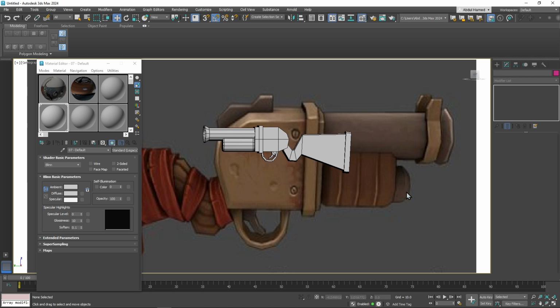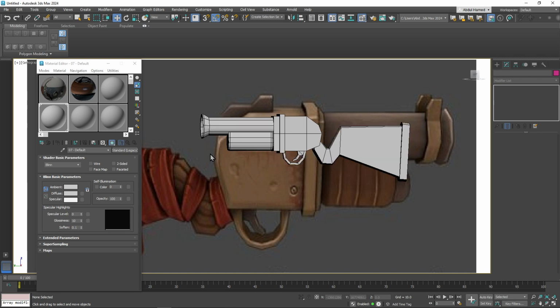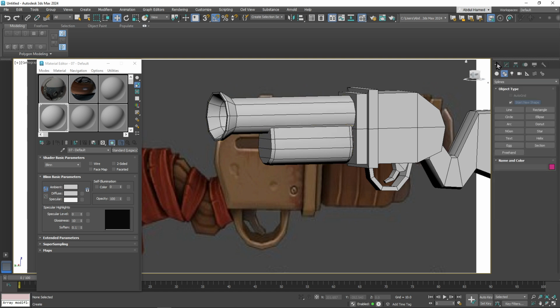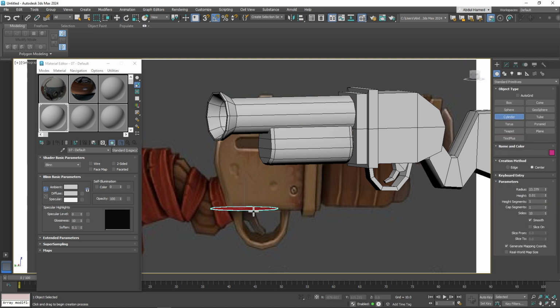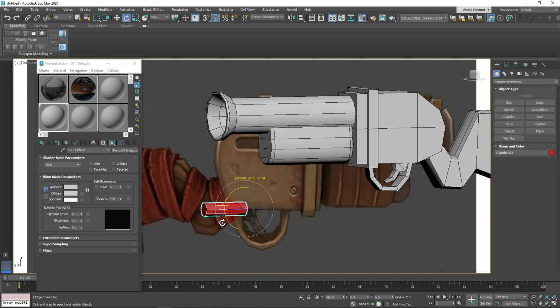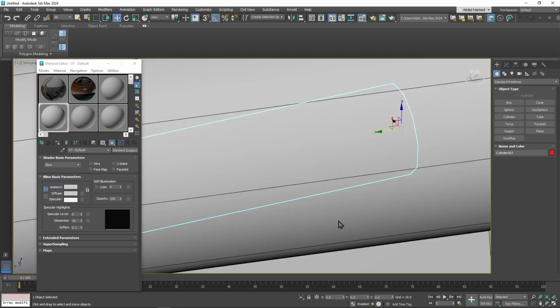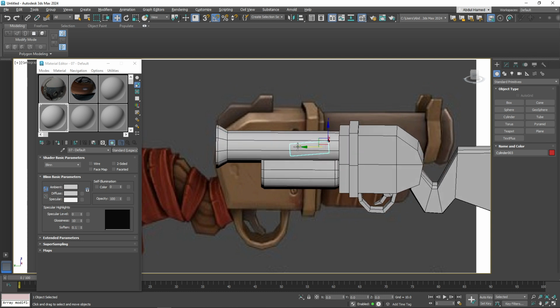And right here we can see another piece. So how do we do that? This is simple. Just create another cylinder and taper it at the top. So cylinder, rotate 90 degrees, center it. To frame the image all you have to do is just click Z. So this seems not to be correct. Yeah, now it's good.